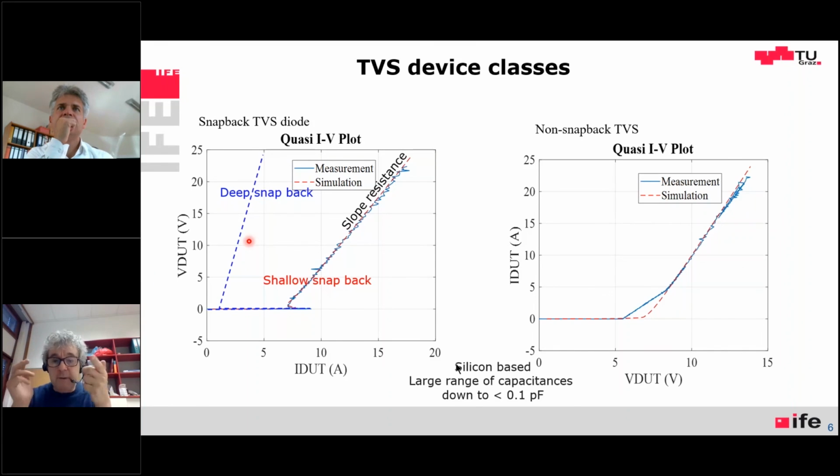We work on both, but for an RF front end or an amplifier where you have to do protection, one has to be very careful what to do. There are many TVS diodes. They're made to produce not so many harmonics, but none are perfect. So in general, the best protection is a linear filter. If your signal is around 1.8 gigahertz, then of course you can make a bandpass filter, and the bandpass filter will push away most of the ESD. So that's ESD protection by a bandpass filter.